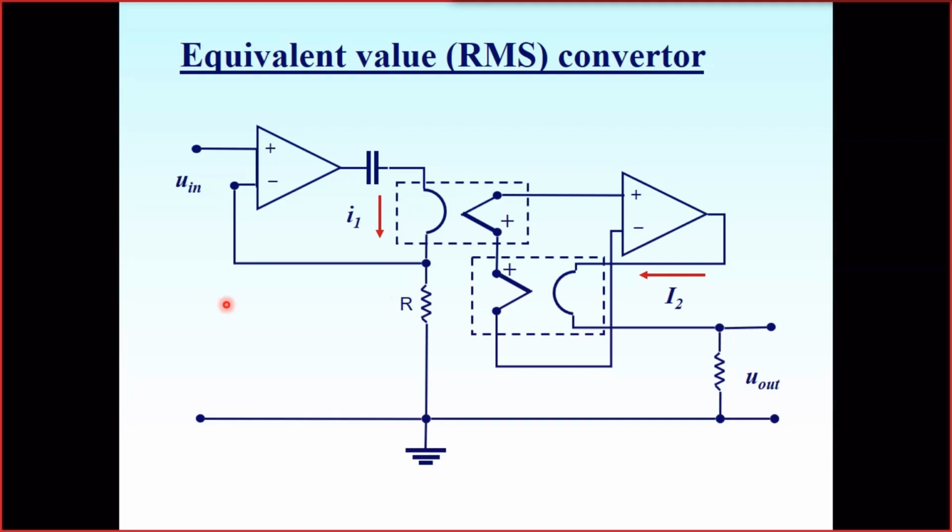It may change with the temperature, it may be heated by the input voltage and change its resistance. This voltage to current converter, because of the feedback due to the operational amplifier, keeps the current always more or less constant. Another feature of this circuit is that it has a very high input impedance. So we convert voltage into current not via the input impedance, but via the infinite impedance of the amplifier. This is probably the most important reason why we use such a circuit.